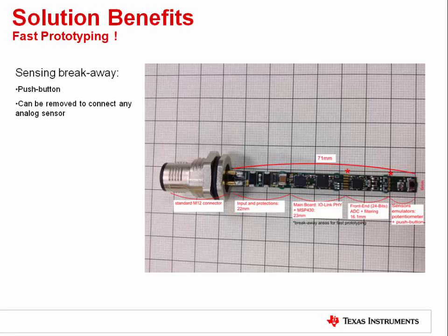Thanks to its modular design, different sections can be easily cut away to allow fast and simple interfacing of any analog or digital sensors. The layout is optimized to meet IEC, ESD, and EFT stress tests. Small 6mm board width addresses industry standard form factor requirements. The FRAM enables fast, secure sensor configuration updates and, of course, helps reduce overall power.